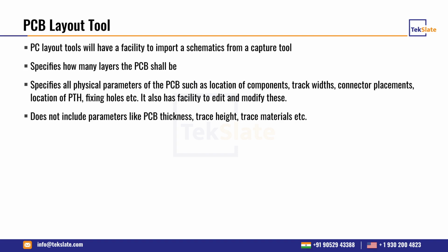That is typically done in the PCB layout tool, and the PCB layout tools have a facility to import the schematics. The schematics that are created during the design process are imported into the layout tool, where you specify how many layers of the PCB you are making and import all the connections into the PCB layout tool. The PCB layout tool by default creates the netlist onto the PCB in several layers, and you can change the track width, the connector placement, location, holes and all the mounting holes, those things you can define. So this is where your actual physical PCB is created.